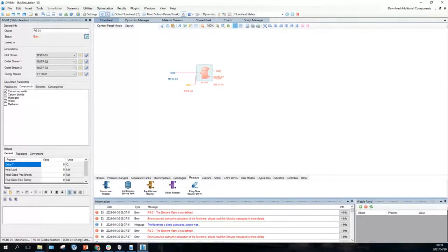Okay. If you use NaCl in the Gibbs reactor, oh, it doesn't solve. All right. Yeah, I tried this when I did the deleting. Once it was solving, I deleted these liquid lines that would be empty, that would have zero flow, and then it stopped solving.